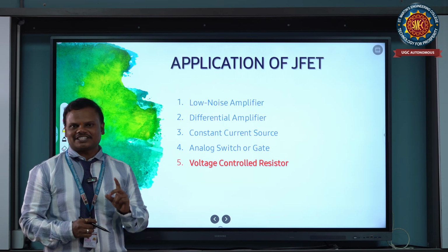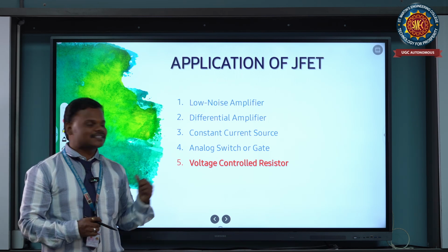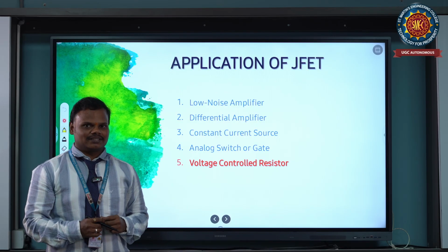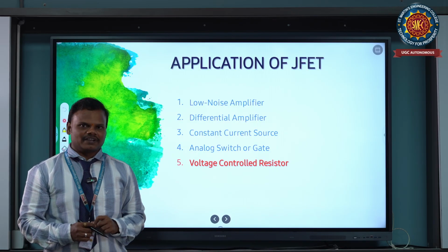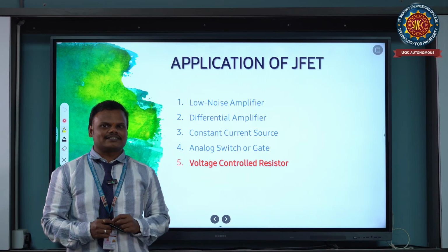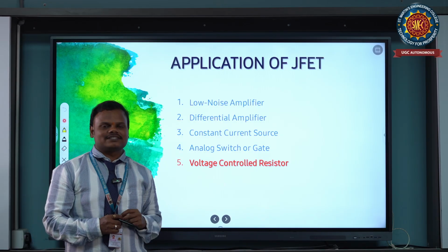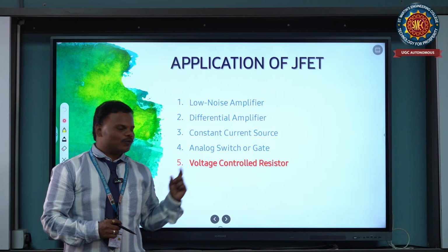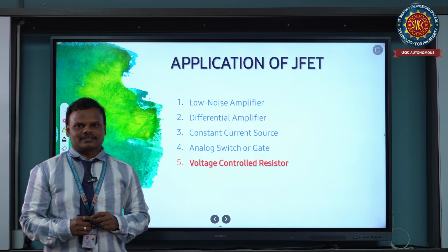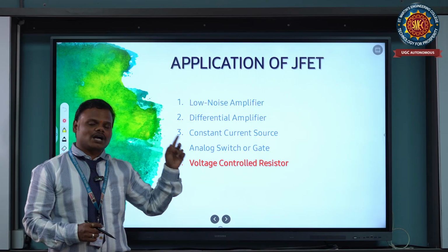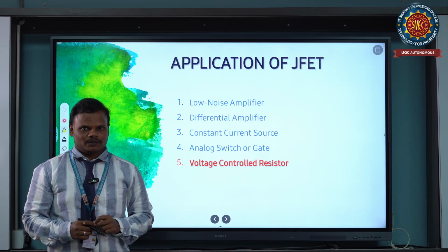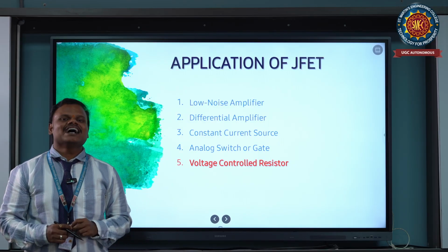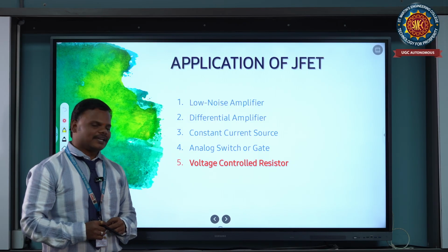That gives a relation between the resistance of the device and the applied voltage, that is, the applied voltage affects the resistance of the device. Hence we can conclude that a FET acts as a voltage controlled resistor, which we also call a voltage variable resistor. These are mostly used in communication equipment.